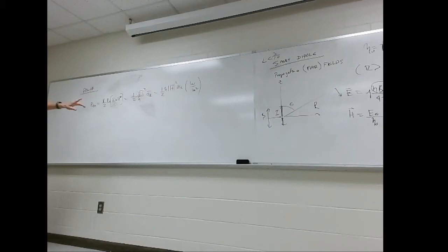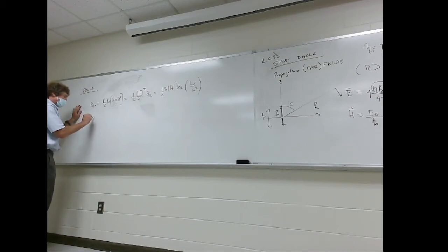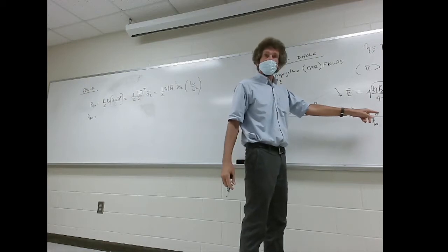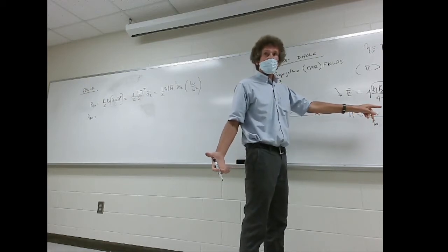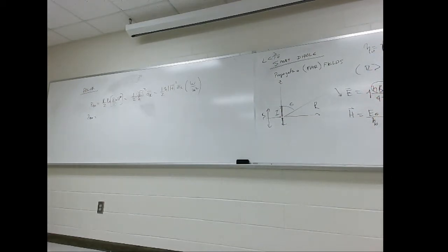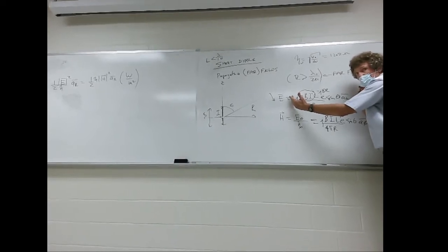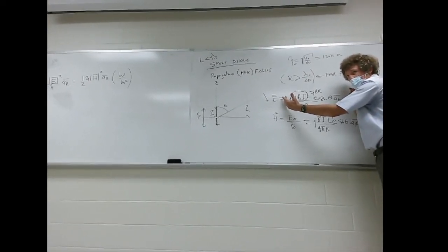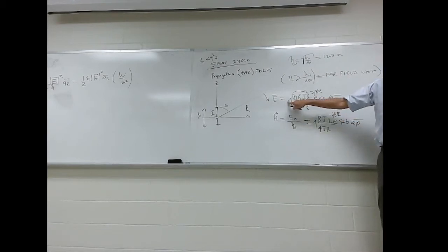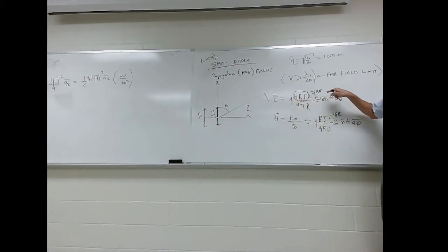Now look here, if we wanted the power density for that waveform, this electric field, or this H field, it doesn't matter which one we use. If we choose the E field, just listen to me now, I would take this quantity and square its magnitude, right? Y'all with me on that, class? When I square the magnitude, that j goes away, doesn't it? Y'all see this e to the minus j beta r goes away also. That's a phase term.